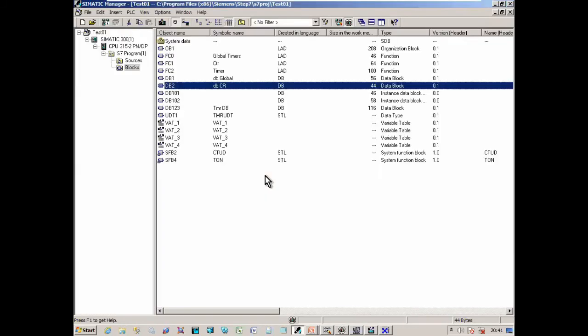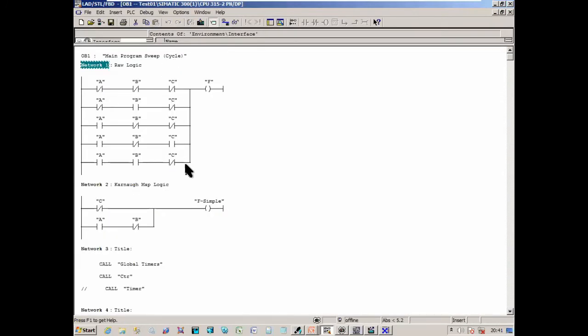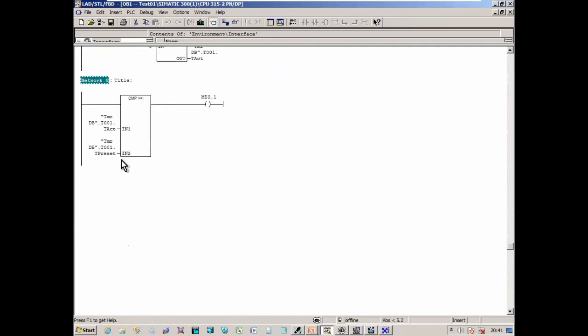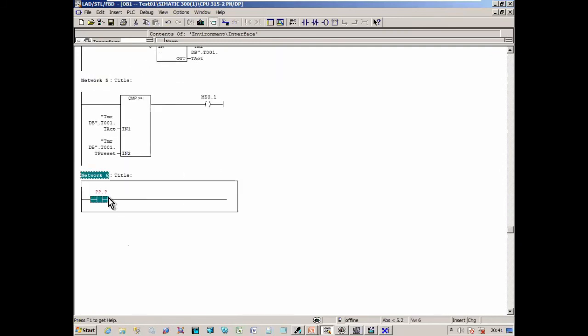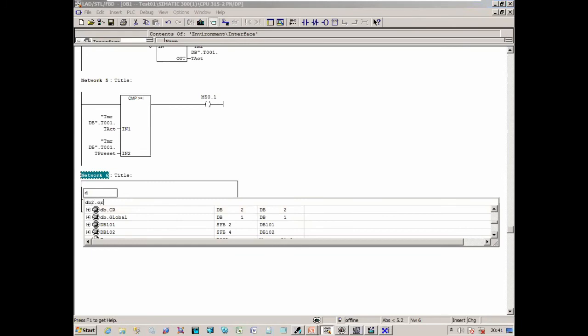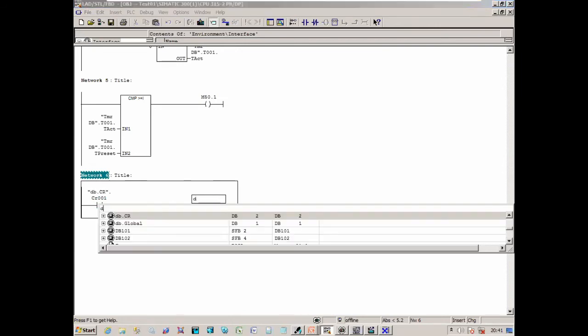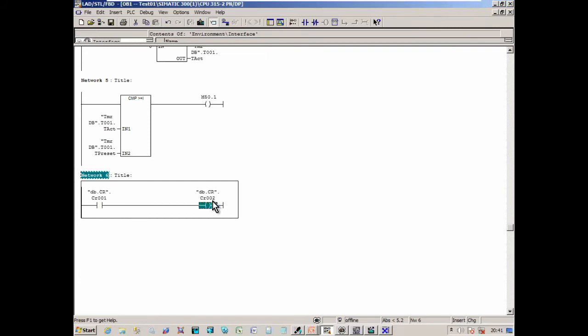But if I go back into my PLC, I go back to OB1, I'll just go to a new rung here, go Control R. I just press db2.control_relay001. See there it says db2 control, but if I move the mouse over it, there's the comment I put in. You see that? So if Tim is great, then we can start the plant. So let's go control relay 02, and there is my logic. See, start the plant now.